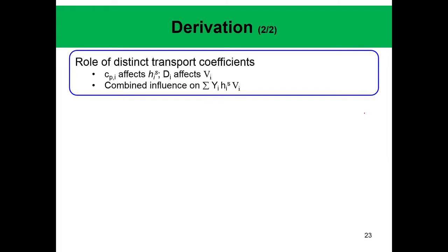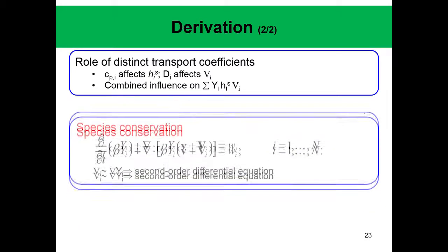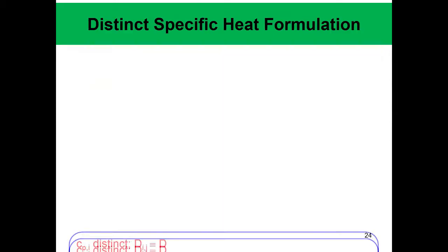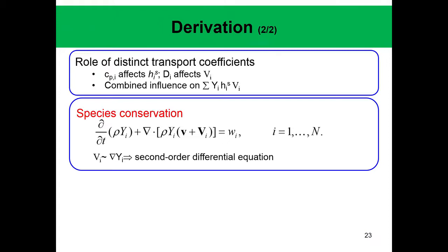So, now we need to basically see, as we have seen, that this is the species concentration, and this is of course the species equation. This is the transient term once again, and this is the convection term, and this term arises once again because the species can cross the control surface with different species diffusion velocities, and of course this is the species production rate term in units of mass.